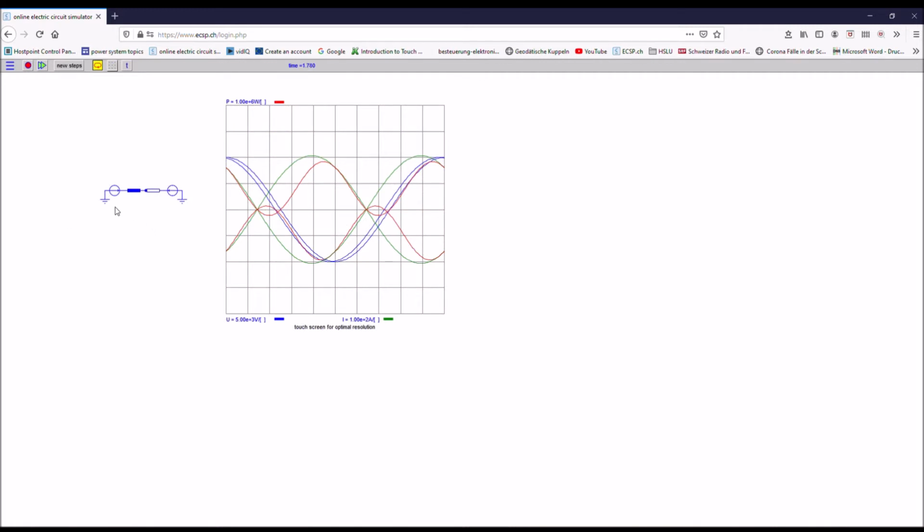So here I have the two sources, 10 kilovolt each one, and then I have some inductor and a small resistor to prevent a DC component to stay forever. Now you can see here I have leading voltage in this source compared to this one. That means that I generate power in this source and I feed power into the other source, which is lagging. And you can see that the power at this source is negative. That means it supplies power.